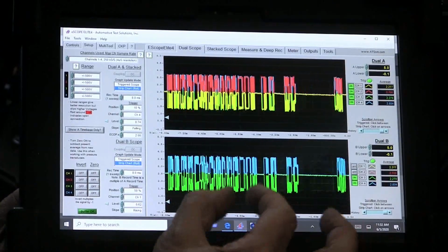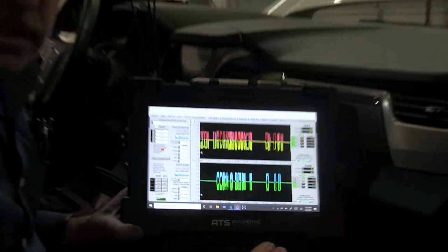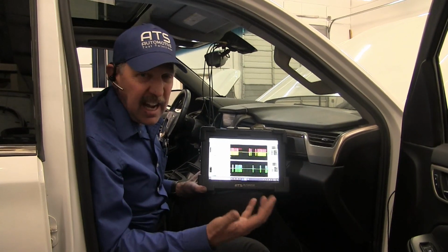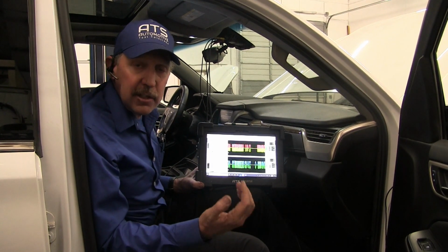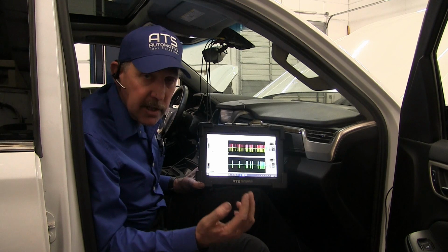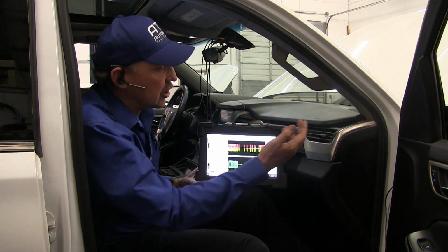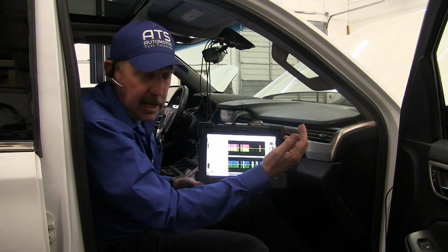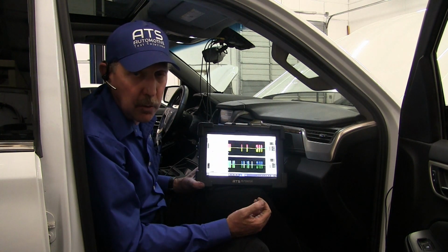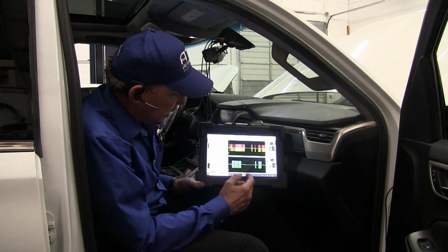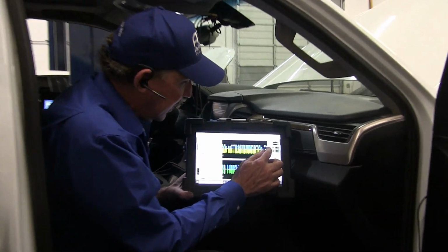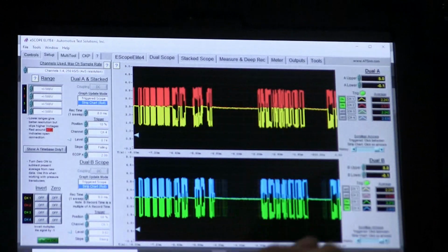You can see how they're covered. That means that the 2 lines going in and coming out have the same data system. On some cars, you'll actually have two different CAN systems in the car. This is the same data, it's just going in, and it's using the camera as a path to bring the two other wires out. So this is the system, and we're going to go ahead and turn these guys off here, and we're going to keep that on.